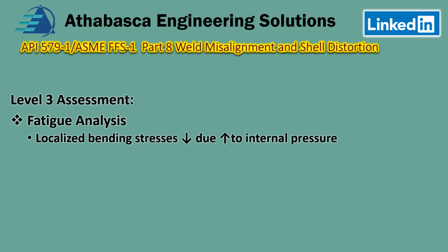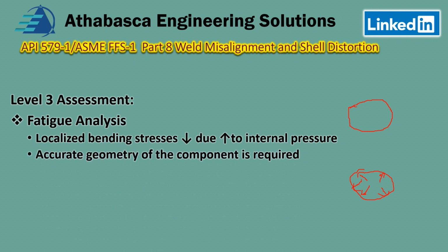If you have a pipe with very little pressure, it can oval. But if you have a pipe with lots of pressure, those outwardly expanding stresses will stiffen that pipe and prevent collapse, because they work against the bending stresses. So that's something you should be aware of.